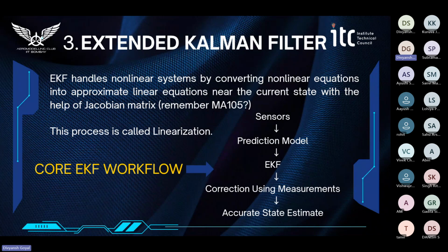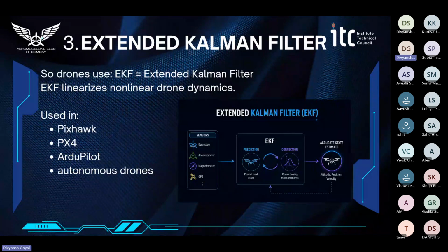Then after getting the reading from the sensor, we send it to EKF. EKF compares both these readings. Then finally, it corrects the reading using the measurement and prediction model. And ultimately, it sends it back to the flight controller and we get the accurate state estimate of our drone. And EKF is also used in Pixhawk. Mostly the modern flight controllers use EKF, whether it is Pixhawk or ArduPilot.